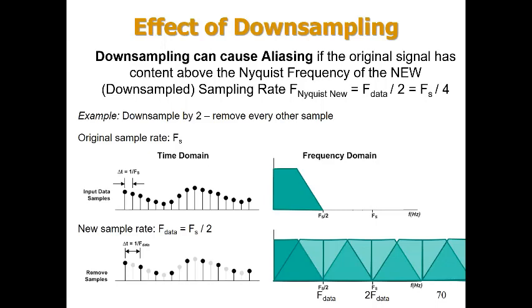All right. So why are we going through this? Well, we're going to look at the case of oversampling as a way to help us do our analog to digital conversion without creating aliasing. We want to look at being able to use a lot of oversampling to make that work really well. But if we choose a sampling rate that's too high, that may not be a rate that I can sustain with the rest of my digital hardware downstream, in which case it may be necessary for me to downsample the data to bring it back to a sampling rate that's sustainable.